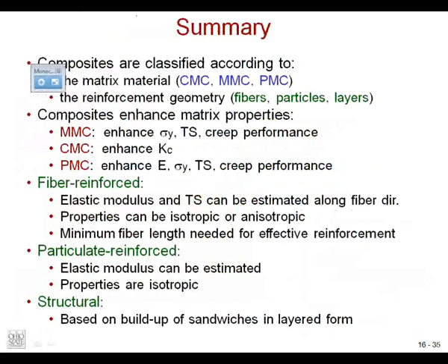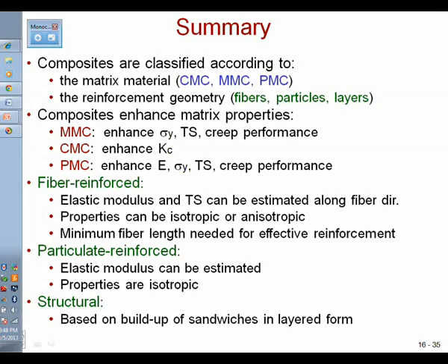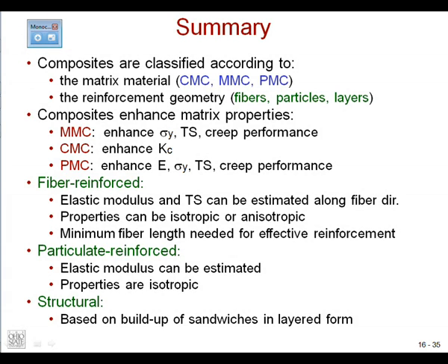Okay, the summary. Composites, we're going to get properties somewhere in between. So what do I want you to know about composites for the rest of your life? We make composites to deal with the bad things of the matrices in general. So that's why with metal matrix composites, the big problem with metals is their density and creep performance. We improve the creep performance, and usually we're reinforcing the metal phase with some kind of ceramic particle that's lower in density.